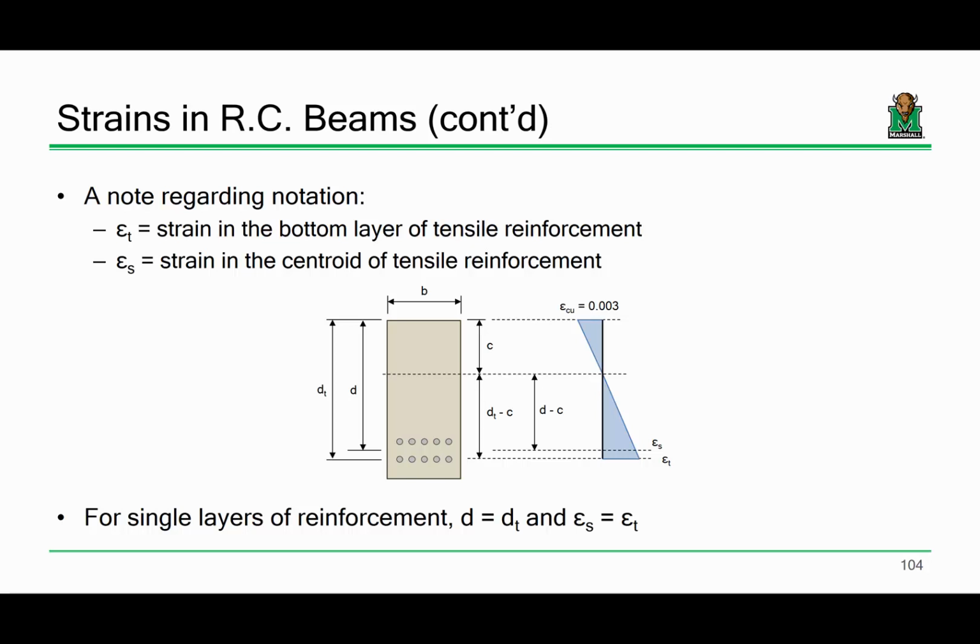So here's the idea. Concrete is a material that behaves very poorly in tension. So in the regions that it's experiencing tension, put some compression in there. Lock in a compressive force that'll negate that tension. That's what pre-stressed concrete is. And so you can get away with using a thinner beam and less concrete, and the beams perform a lot better. Like they can achieve spans that they wouldn't be able to without pre-stressing.